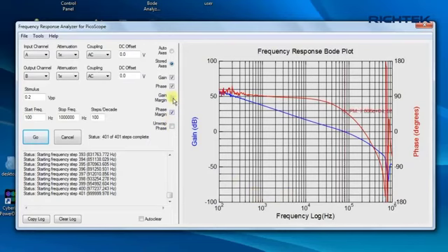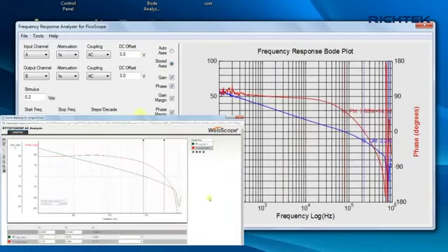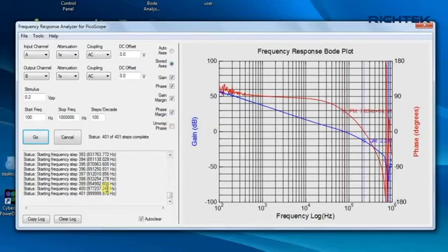Check the phase margin and gain margin boxes to show the values in the plot. Use the mouse to zoom in. The crossover frequency is 78 kHz, the phase margin is 52 degrees, and the gain margin is 13 dB. The simulated values showed slightly higher phase margin, 62 degrees. This difference is probably caused by tolerances or model inaccuracies.